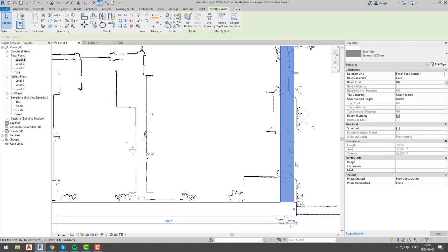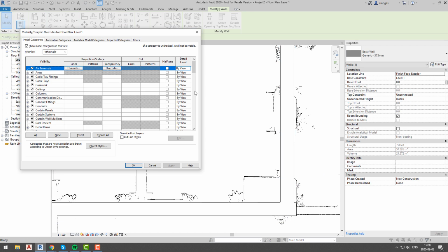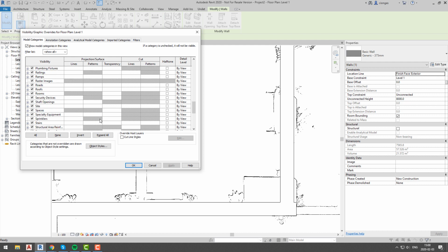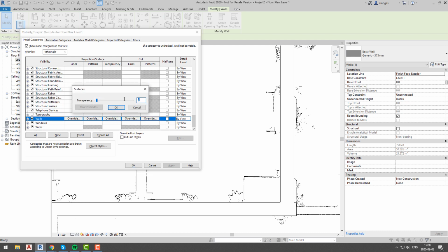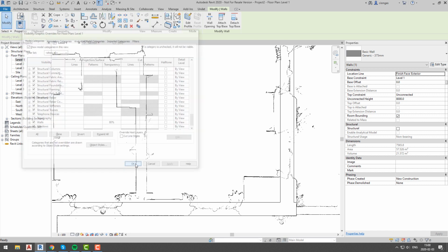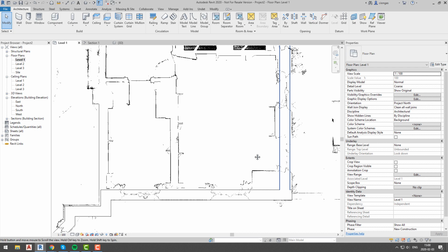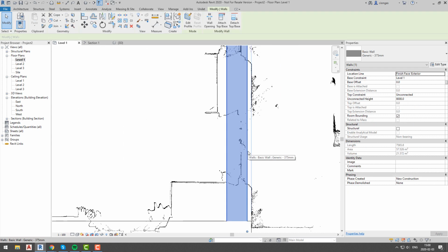Visibility options window can be called from properties window or using keyboard shortcut VV. So now we are adjusting thickness of external walls, also we are adding internal walls. Since this process is the same, we are just following walls outlines using dynamic image information. We will fast forward this part.